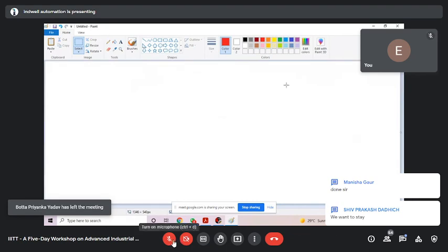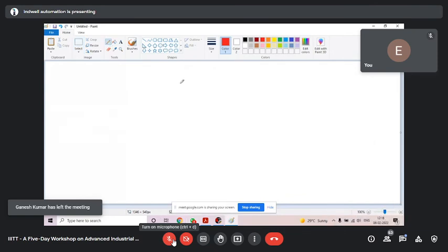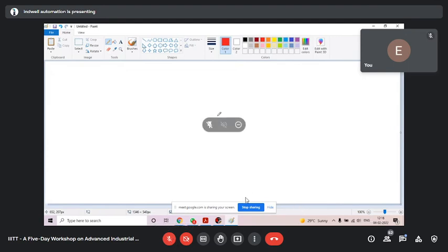I was asking about that K1 for from module. That last K1 is again bit length. Like you want to store that in one memory, or you want to store in consecutive memory. Okay, so I wanted to store that in D0 only, so I have given there K1.